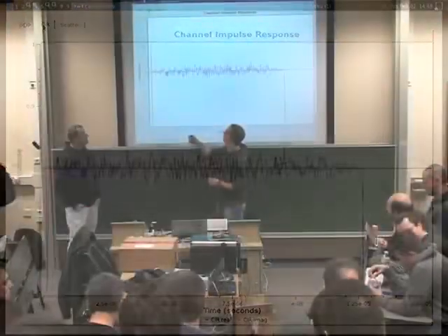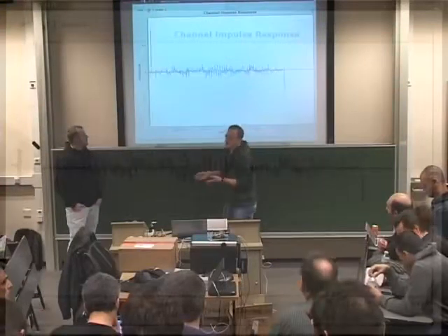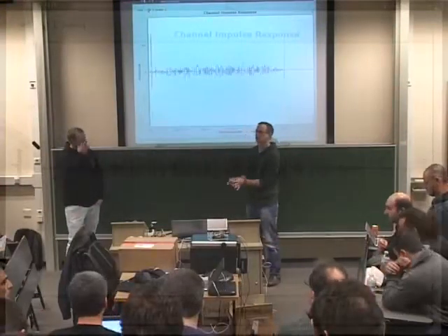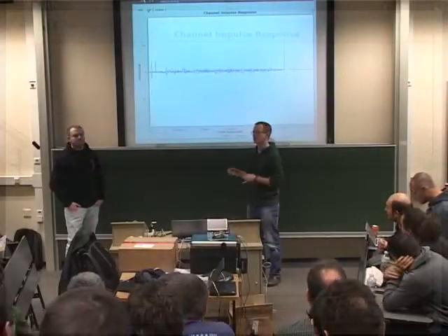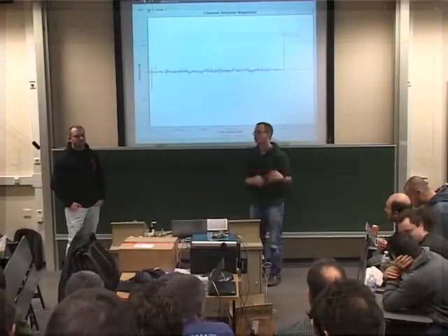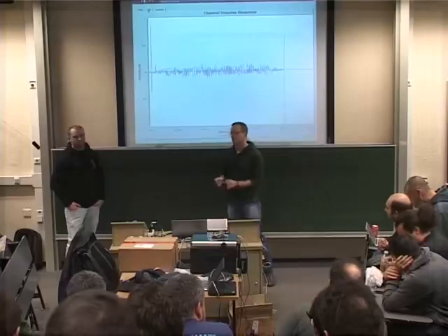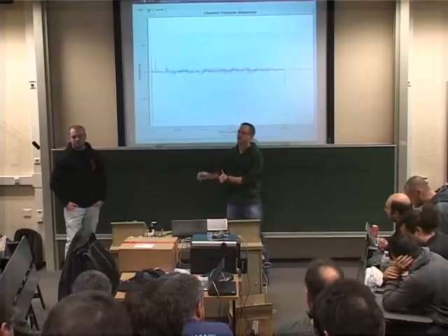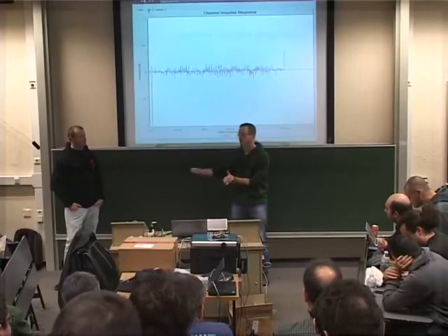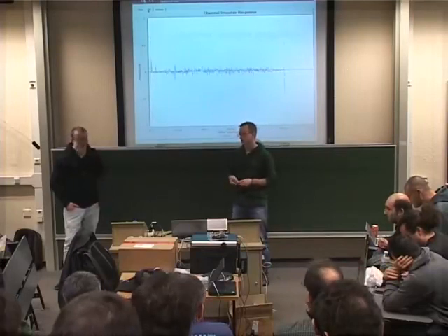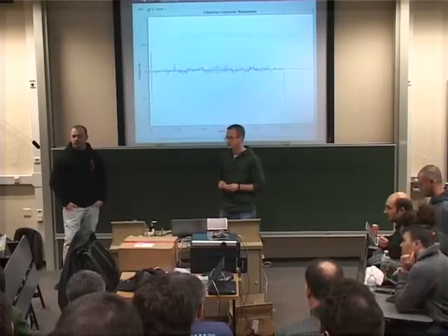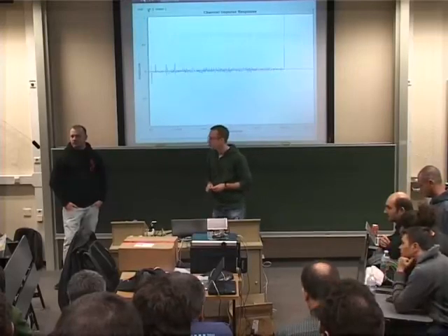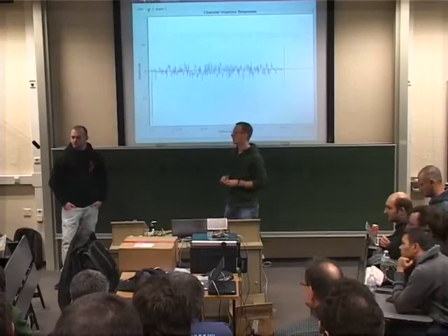It can happen from the Doppler frequency, but it can also be that the oscillators are drifting apart. That's the reason why in the channel sounder we use those GPS DOs. We wanted to measure the Doppler shift, but you have to know whether the shift is based on the Doppler or because the oscillators are drifting apart. Okay, so you use that as a reference oscillator, so you have a stable frequency. Yeah. If you want to simulate bad hardware, that is possible.